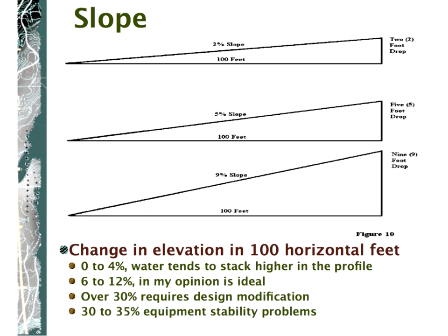So if you have, say, 20 drip lines, one above the other, 2 feet apart, covering 40 feet, then that bottom is likely to get very, very soggy from the water coming down from the top. So typically on this sort of slope, you'll probably only want about 5 drip lines in a zone, and then a considerable space before you get into the next zone, to allow space for that water from that zone to percolate deep below the water coming in from the zone below. I trust that's clear.